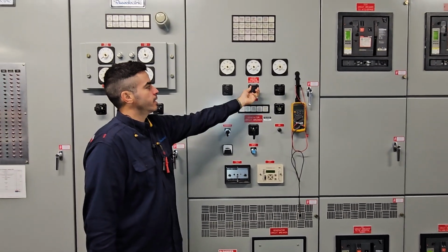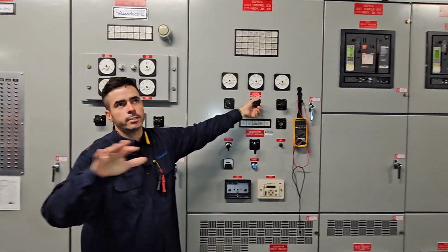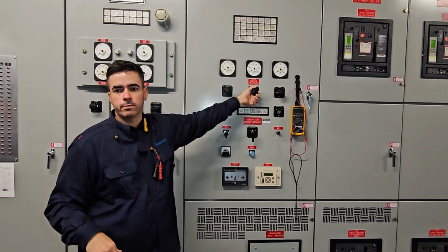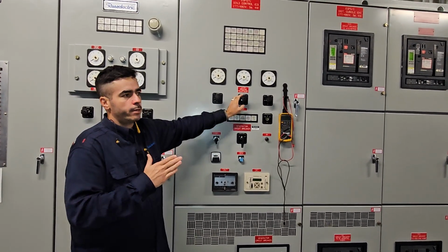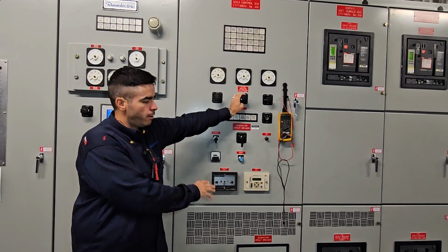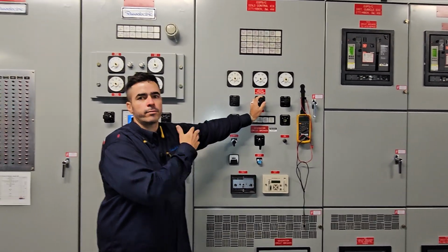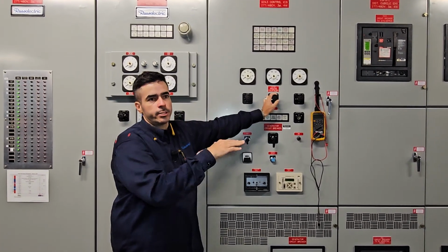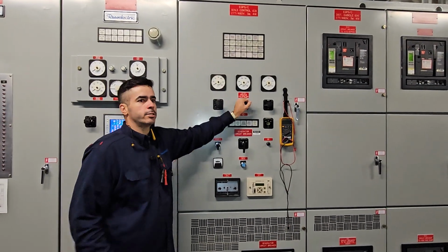And then finally, when the start signal is gone, because the ATS transferred back, or we are done with the no load test, we keep it on auto. The generator will automatically open the breaker and go to cool down. After 5 or 10 minutes, whatever it says there, it will completely shut down and remain with no alarms. Okay? Questions so far?